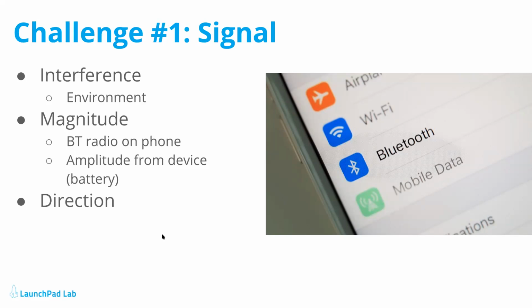So there's two main concepts there that we're trying to figure out the best way to communicate to the user: the magnitude, or the signal strength, as well as the direction. The magnitude is fairly easy to determine. The Bluetooth radio will tell you, okay, I'm at this signal strength, this decibel reading, which is great. But it's more of a radial concept. You don't necessarily know which direction the signal is coming from, and that makes it difficult to develop a finding experience for that.